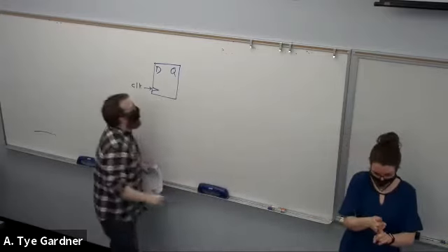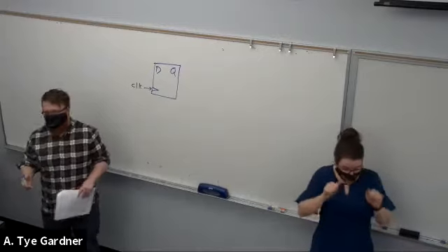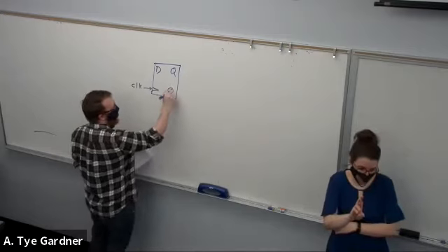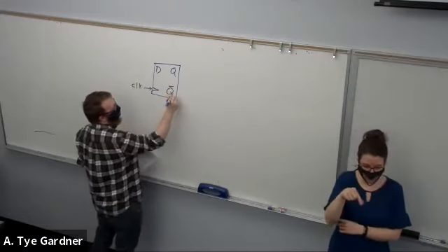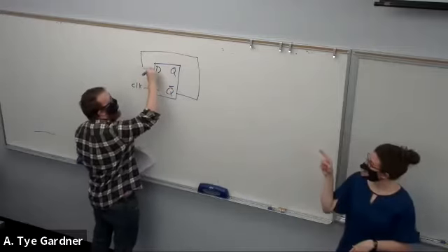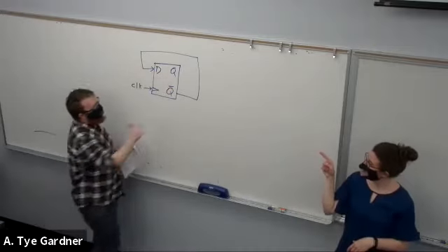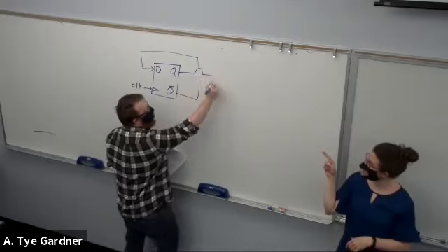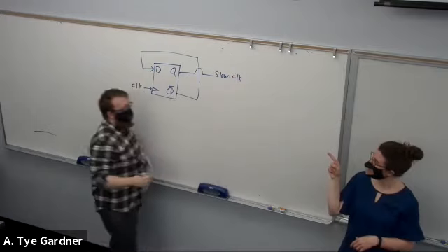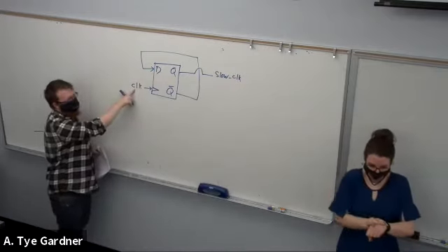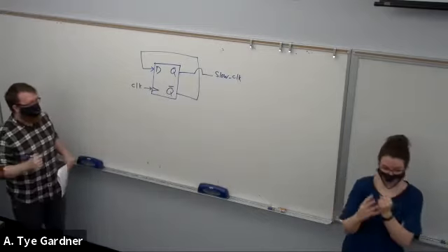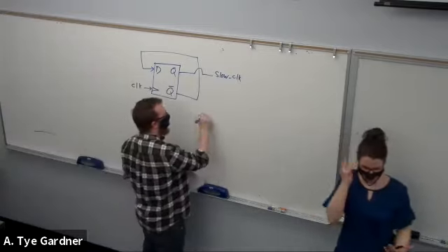It turns out we can build clock dividers, as they're called, really easily using D flip-flops. The way we do that is simply taking Q bar and feeding it back around to D, and then Q is going to be what we'll call slow clock. So we're putting in the fast clock and we're getting out a slow clock. Now, why does this work? Well, first off, I shouldn't have erased my clock.